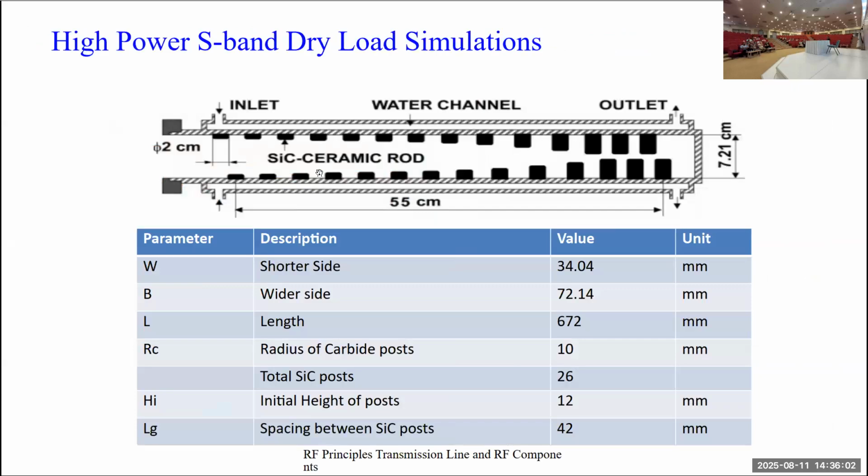Now, the next thing is, when RF power is reflected back, you have to dump it somewhere else. You don't allow it to go to your amplifier or RF producing devices, because reflected power goes to that amplifier and disturbs its stability. So these waveguide components which dump RF power are called water loads or dry loads, depending on what sort of material is used.